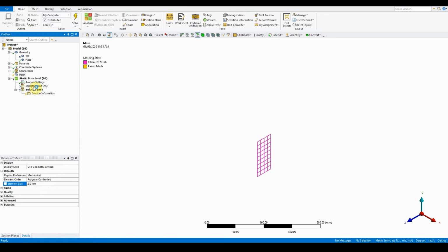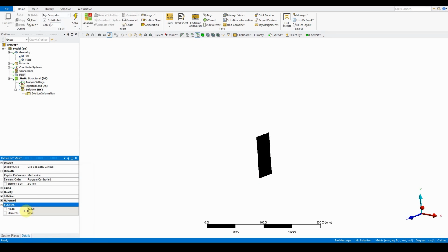Generate mesh. So it's a bit smaller. However, we do need to look at the number of nodes, and I believe that's exceeded the student license element number, which is 22,000, I believe, or 29,000. I think it's around the 30k mark. Let's leave it as it is, and then let's see if the software tells us if it's not.